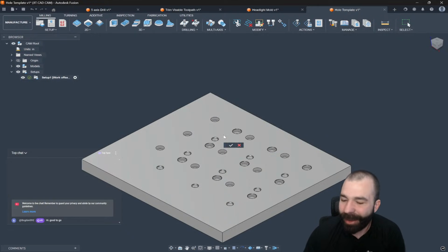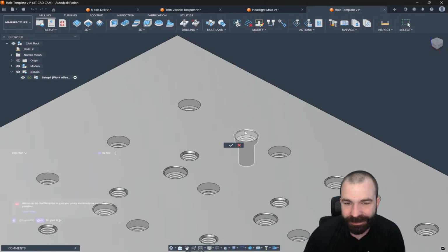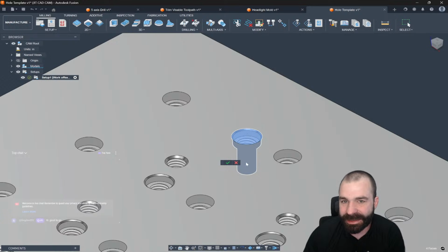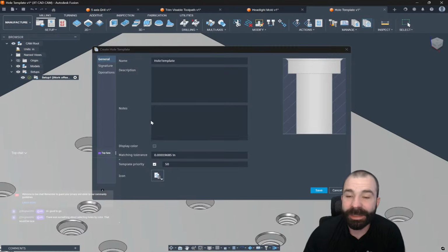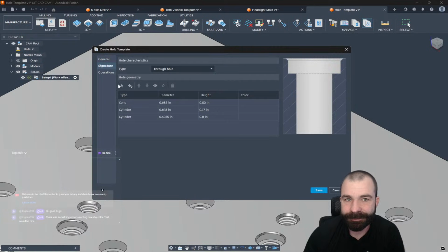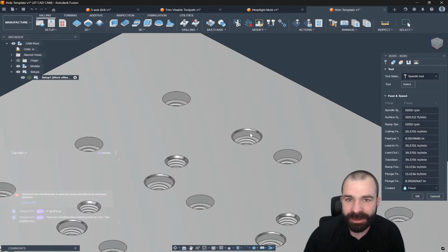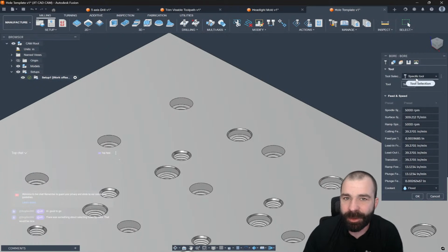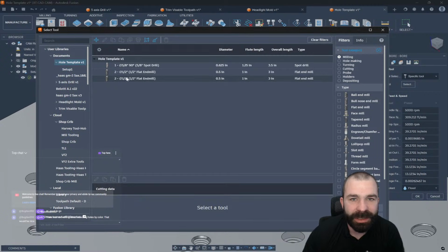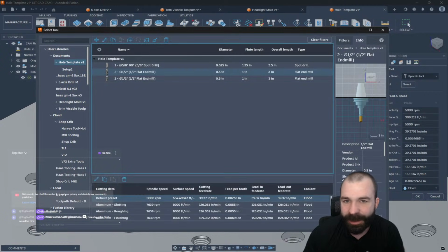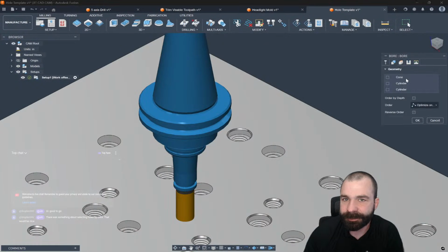So what it's now asking me for is the selection, which is pulling the entire part or the entire hole signature. And as you guys can see, we're going to leave this alone, but it looks like we're going to have to add in a couple of operations here. This is actually pretty neat. So what I'm doing is building a generic kind of situation. Let's pull my tools back in. There's my 1/2-inch flat end mill. Geometry is going to be the cylinder.